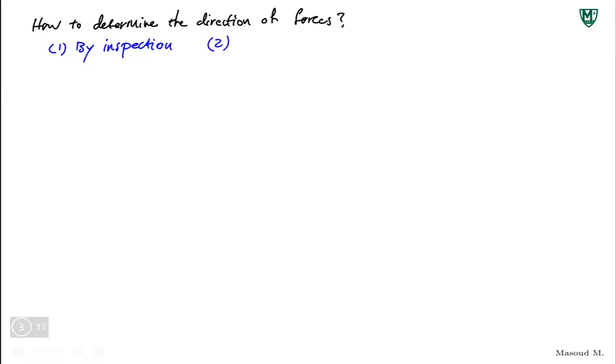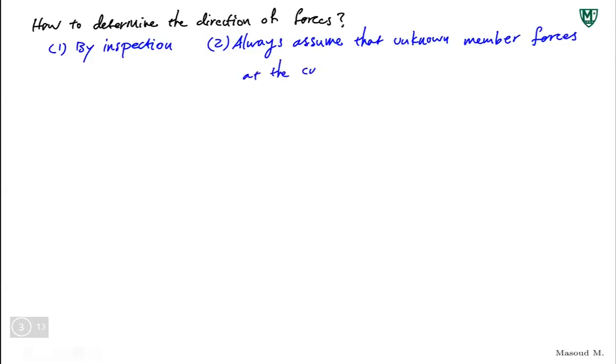Two, always assume that unknown member forces, the forces related to those members, at the cut section, are in tension.